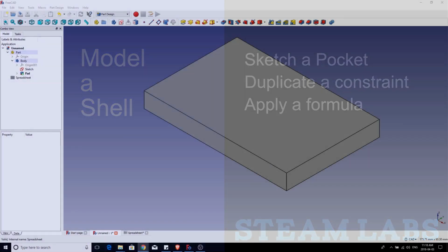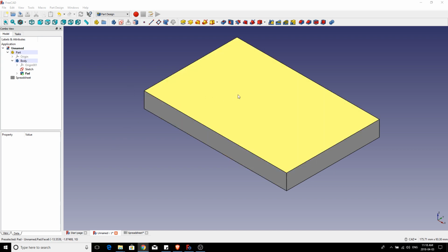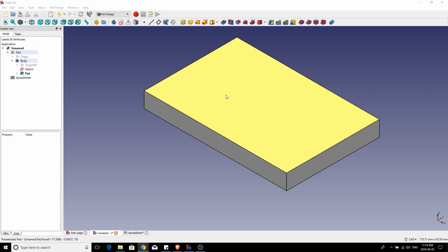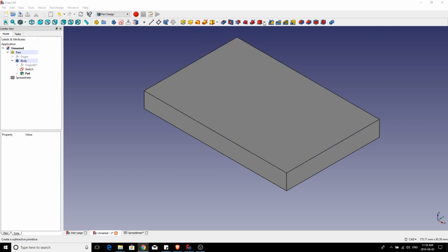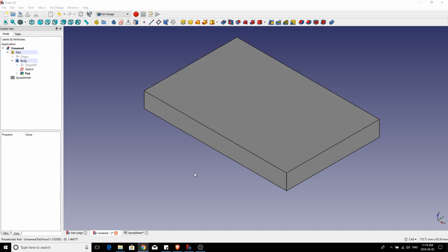Okay guys, we're doing really good here. We've got our parametric box ready to go. And as I move my cursor over, you can see that I'm now able to highlight the various faces of the box. So the way that it works in most CAD programs is that you always come back to using sketches. And once you have a face made, you can actually apply a sketch to it exactly as if you were drawing on it with a marker, and then you'll be able to apply operations like you see up top here to that new sketch that you've created on the face of your object.